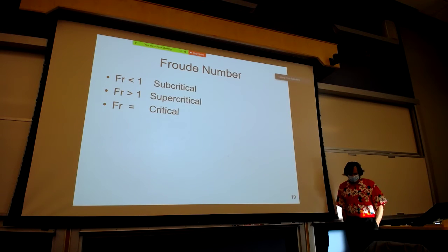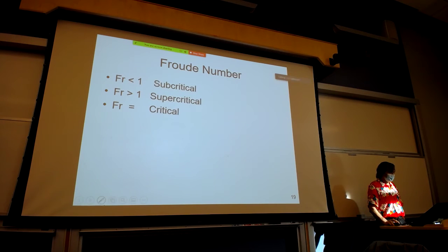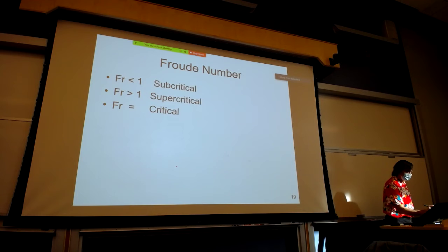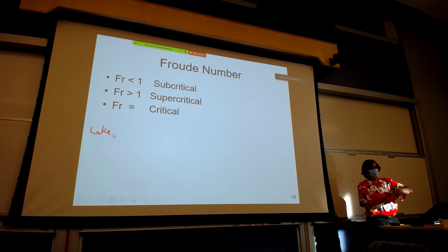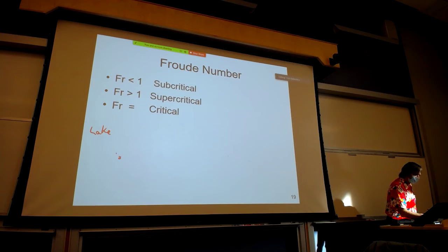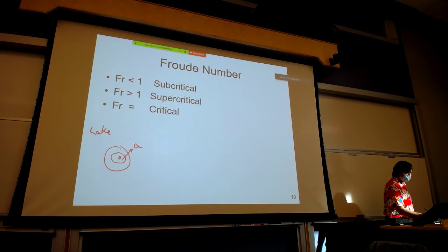So, continuing with this example, but talking about something that we discussed last time. Last time I introduced the Froude number. And you've actually seen this before when we were talking about the hydraulic jump and the sluice gate. But if we had a lake, and 8 days from today, on Saturday, December 19th, you take your fluid mechanics book and you throw it into that lake, what you would see are concentric rings moving away from where you throw the book. And these move at a velocity we're going to call the wave celerity, A.